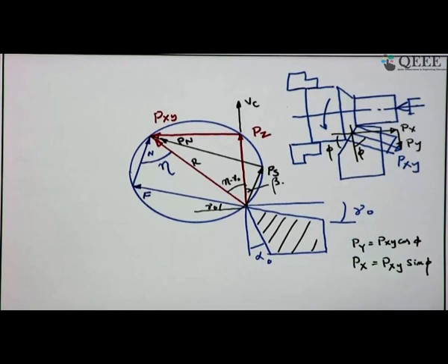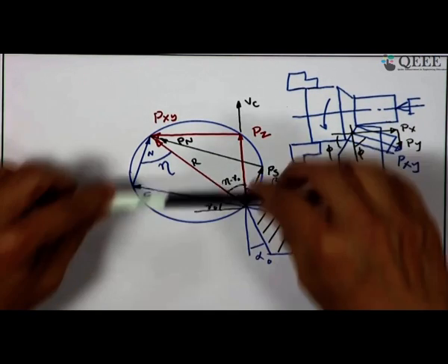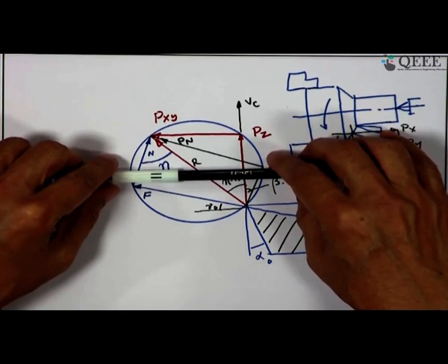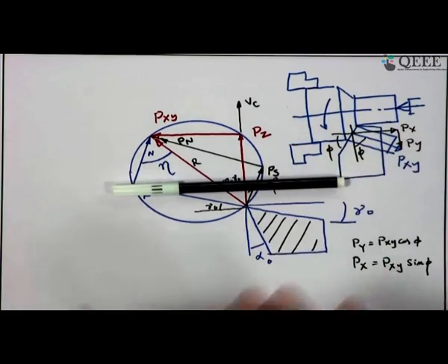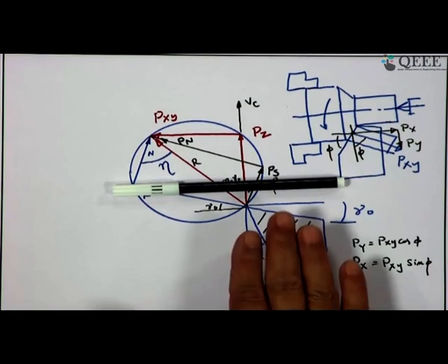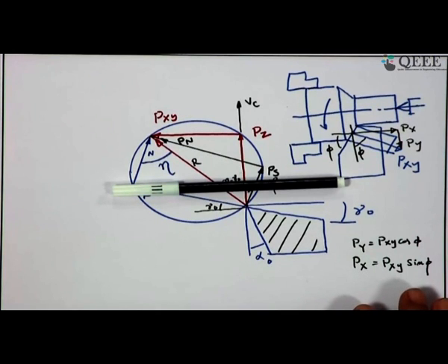Suppose if it is a slender job, say maybe a slender job like this, what I put it here, and then L is quite large compared to the diameter. So, with little push it will be like a bow shape. So, this is not permitted.